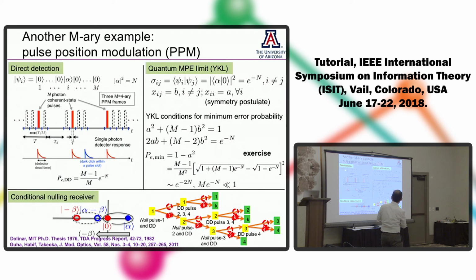They use this modulation format where M is around 256, in the Lincoln Lab program that set up the Earth to Moon laser comm link. And they used a superconducting nanowire single photon detector, which is a form of single photon detector. So they are limited by this error probability, although they also had dark clicks from the detector. So that's what they currently use.